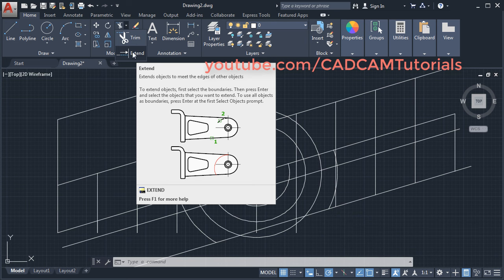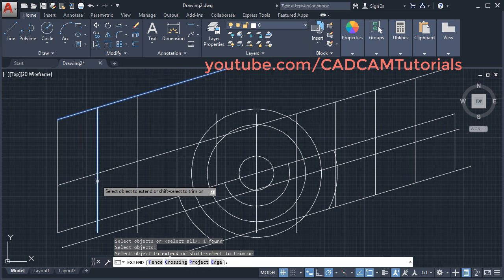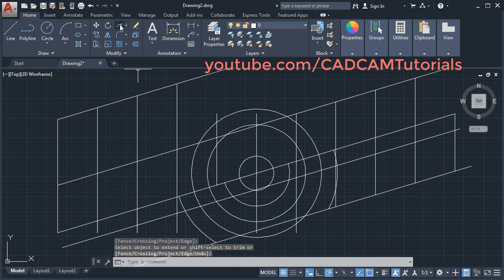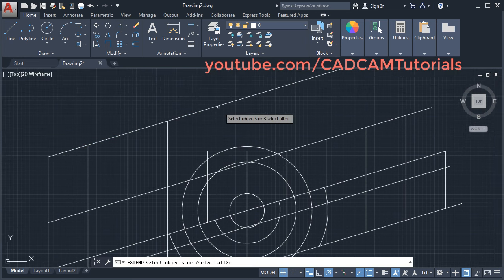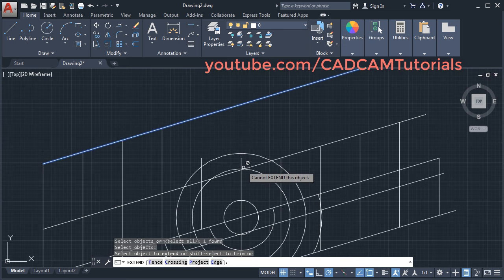Click on extend. The process to use extend is the same as trim. That means at first you will have to define the object up to which you want to extend. Suppose I want to extend this line up to this line. So click on it, then press enter, then click on the object you want to extend. So that object will be extended up to that object. Press enter to stop the command. Extend, then select the boundary edges, then press enter, then click on the object you want to extend.